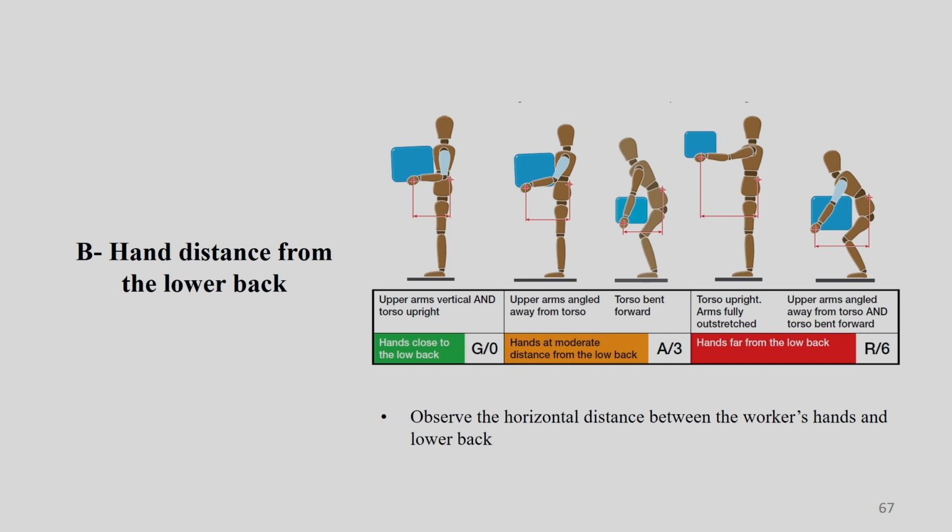And when your CG is moving away from your body, there is always a chance that you miss the balance and you fall, right? To prevent that, your postural muscles which are responsible to hold those postures will be active and keep on working, and that is going to cause some fatigue, and slowly the accumulation of that fatigue may cause musculoskeletal disorder, or musculoskeletal discomfort.